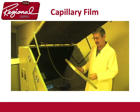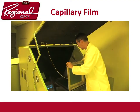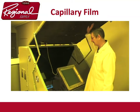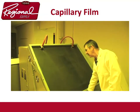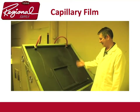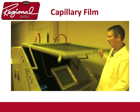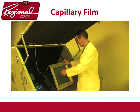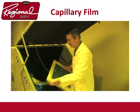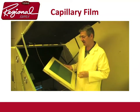Now that the screen's dry, next thing is mount your positive on your screen and expose it. So I'll just put it in the exposure unit, set my time. We got 180 units, and I'm going to close it down. Okay, it's now exposed. Vacuum's gone. Open it up. Remove my positive and bring this into the washout area and develop it out.